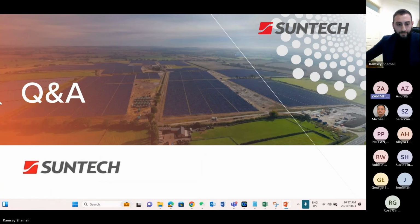Yes, Ramsey, just a quick question in regards to the warranty for the TOPCon PV modules. Is it 15 years or 25? So we want to be specific with the models because there are differences between the residential domestic ones and the utility. If we're talking TOPCon PV modules, we have our residential Ultra V Pro minis, ranging around 440 watts. These ones are 25/25 or 25/30 for the bifacial double glass model.